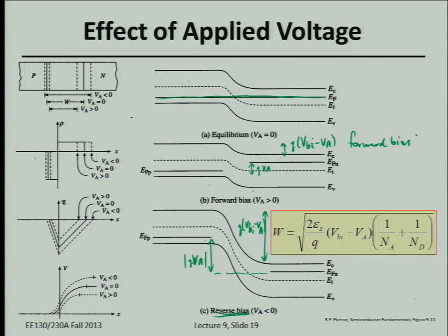Because as you decrease that potential barrier to diffusion of carriers across the junction, the current density will grow, and the diode will heat up eventually, and it'll melt before you can actually reduce that potential barrier to zero. So just keep in mind that the potential barrier can never be reduced to zero in practice. There's just physical limits.